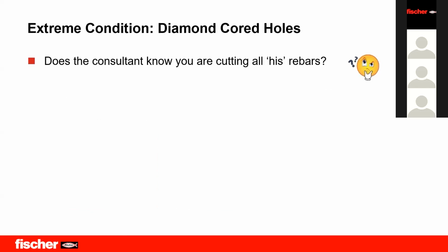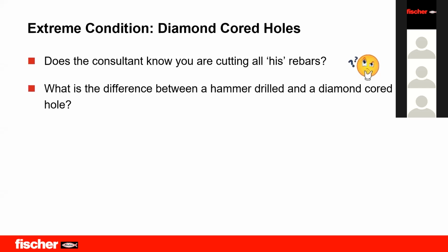So first of all, the question is, does the consultant know you are cutting all his rebars? Yes, for sure, the consultant should be aware that you are cutting the rebar, because the design of the structure stands on the reinforcement, and he should be aware that yes, we are doing a core drill for some other applications.